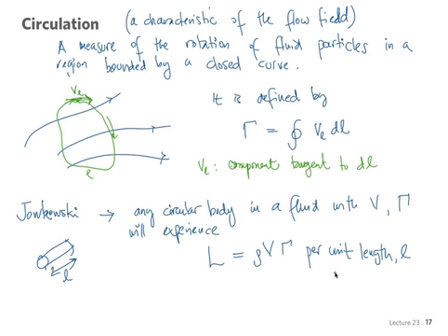Okay, so this is a very interesting result that we can use to apply ideal flow to some explanations of lift. So what does this imply for an airfoil? So we study then what's called two-dimensional wing theory, two-dimensional in the sense that we're just looking at a cross-section of a wing that is assumed infinite on both sides, just to be able to use two-dimensional theory.